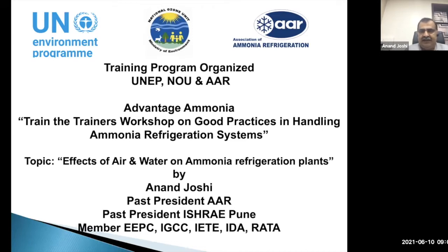And secondly, these synthetic refrigerants are mostly mixtures of refrigerants. It means they are a combination of different gases. So when such a refrigerant leaks, you don't know which kind of gas has leaked, and you have to remove all the gas and charge the new one. It does not happen the same with ammonia. Ammonia can be simply topped up. Puranikar sir has already explained on day one what the other advantages of ammonia are.